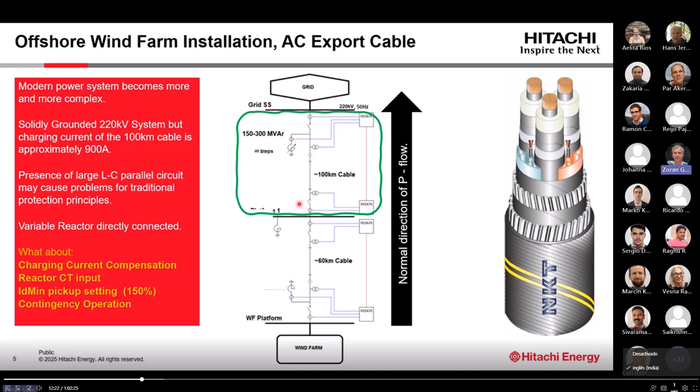If you have a relatively weak system, whether from a fault or under some conditions, and you need sensitive pickup, then classical differential will run into trouble. Therefore, it depends not only on the cable but on where you install that cable.